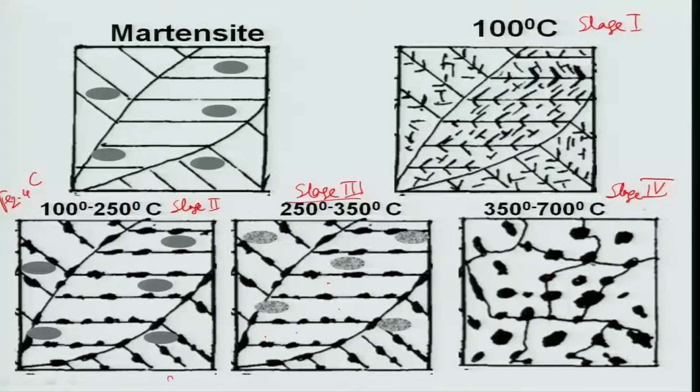These are all the spheroid cementites, and this is routine in the high temperature tempering treatment of the Martensites. So, you have seen that there are stage 1 to stage 4 in the Martensite transformation depending on the temperature you use. I have not talked about time. Time can vary from 1 day to about 3 days, depends on what you actually want to get.